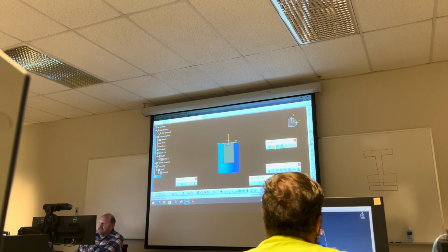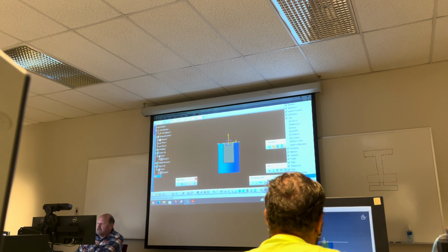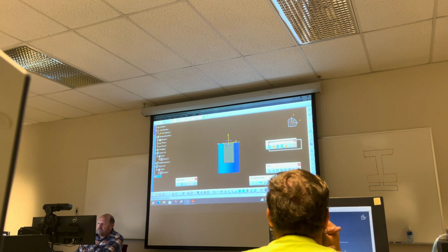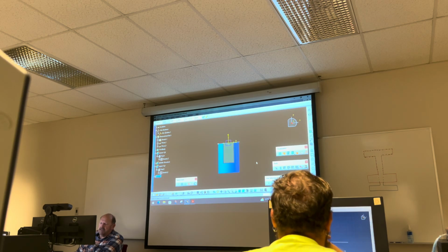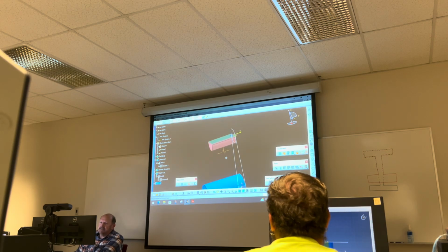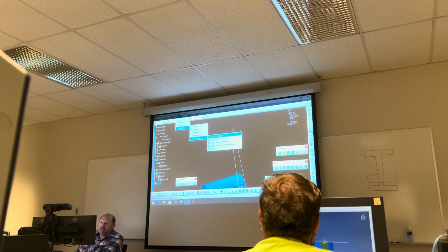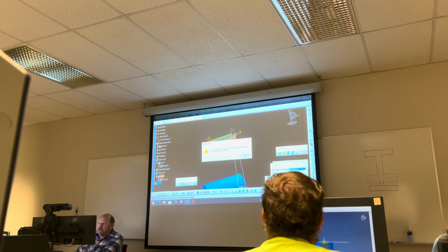This thing under visualization, cut part by sketch plane. You may not have it turned on in your toolbars. Mine's turned on. So we need some reference elements, or we need some construction geometry out of this. What I'm going to do is, I'm already in this sketch. I'm going to go in and say insert operation 3D geometry, intersect 3D elements, and let's see if it takes the whole cylinder. Sometimes that's fine.